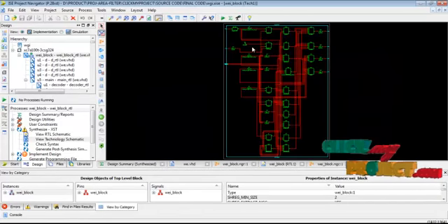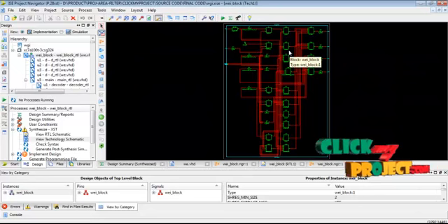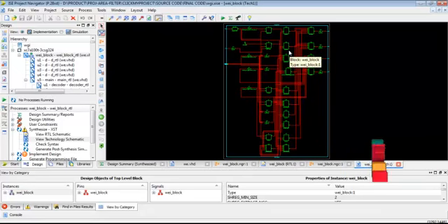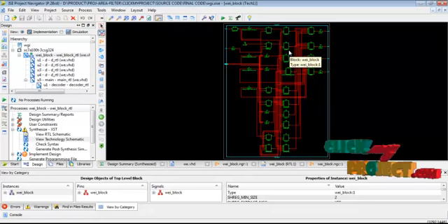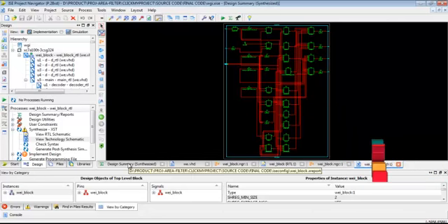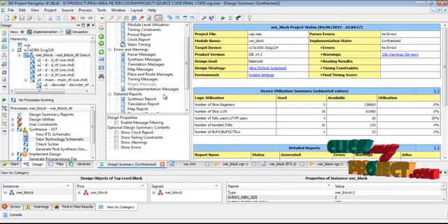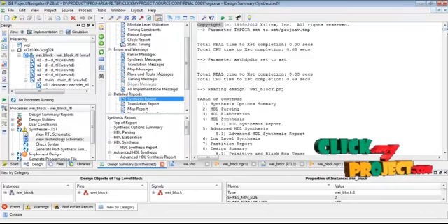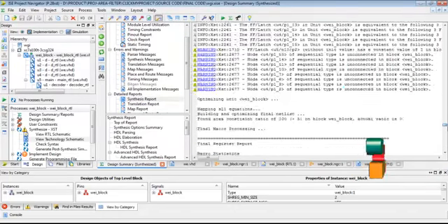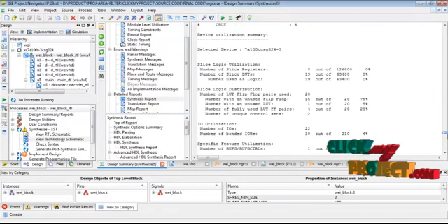represents the lookup tables, input output buffers, wire connections and flip-flop pairs applied by our overall weighted filter architecture. Then we go to the design summary result, then the synthesis report. Just we generate the synthesis report for the weighted filter architecture.